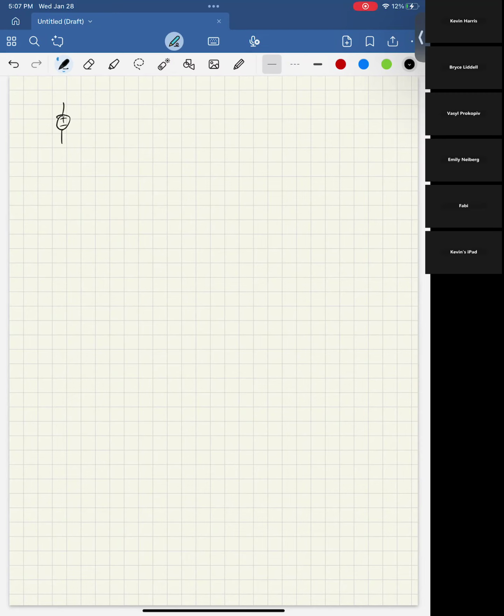So voltage sources are the ones that look like a circle with a minus and a plus, and it has some number. Let's just say it's 7 volts. What this is saying is that between the two sides of the voltage source, there's a difference of 7 volts. So if I have maybe 0 volts here, then here I'd have 7 volts. But also, if I had 2 volts here, that would mean I have 9 volts here, right?